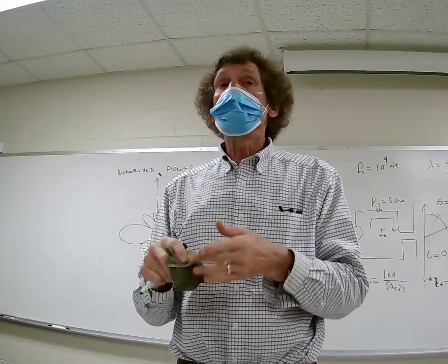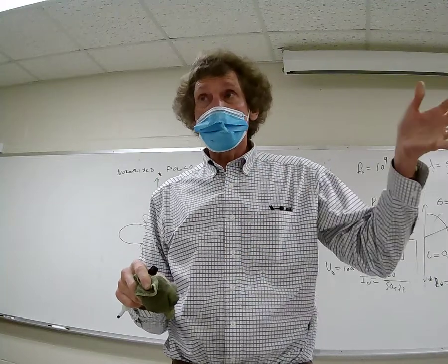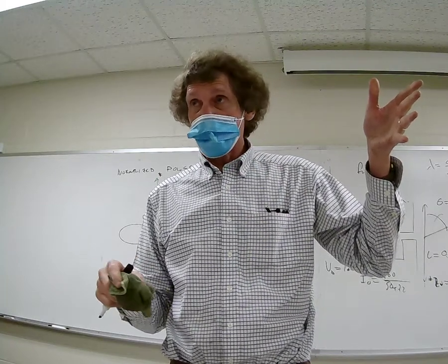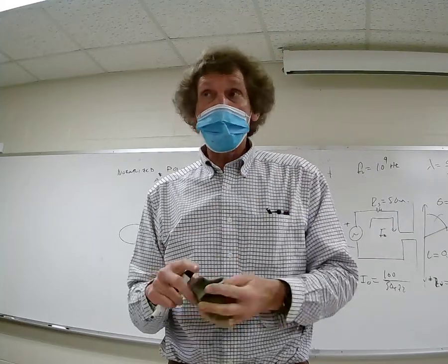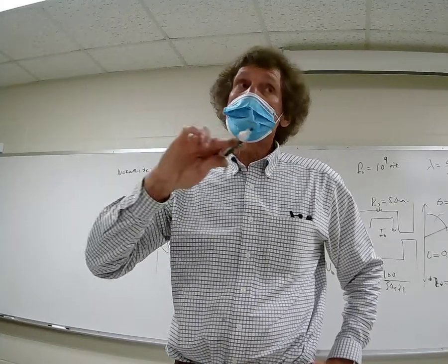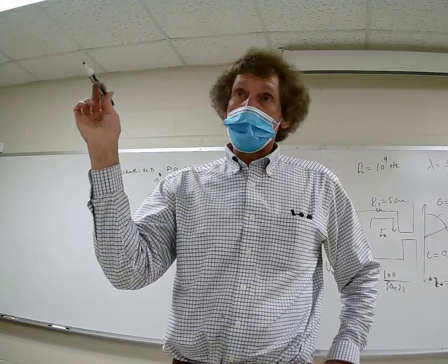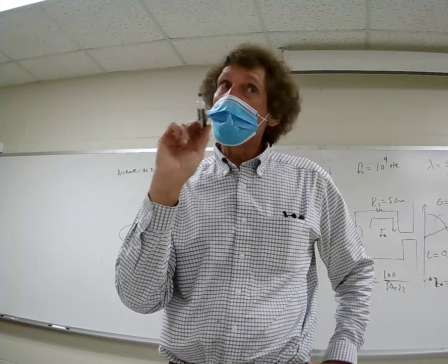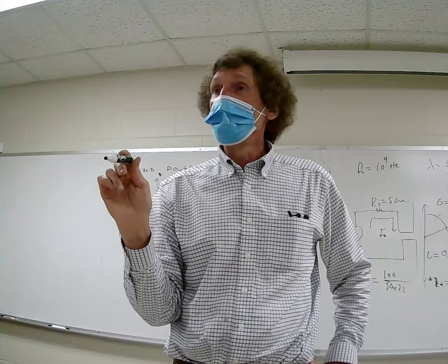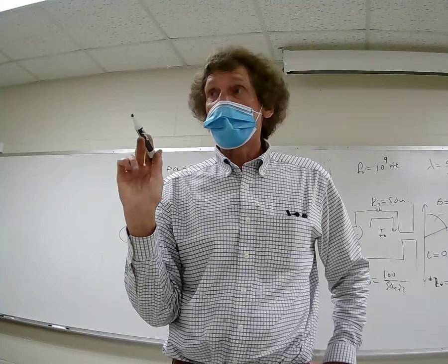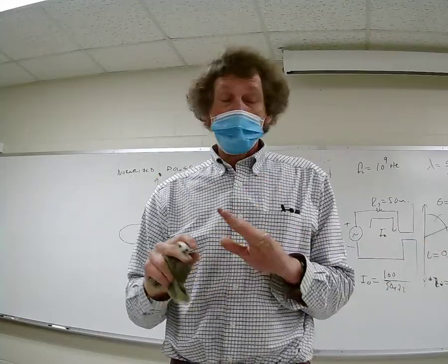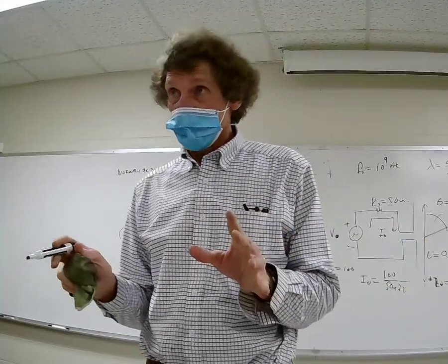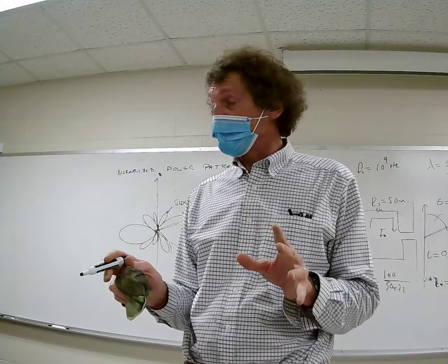I will give you that crazy equation for the input impedance of a transmission line: Z_in equals Z naught times the quantity Z_L plus j Z naught tangent of beta L, lossless or very low loss, where beta is beta in the guide, over Z naught plus j Z_L tangent of beta in the guide times length. You with me on that? So I'll give you that. I'll give problems like the ones we did. You don't have to worry, but you've got to know how to do the calculations. Hint: make sure you run the calculations through a few times and you know what to do.